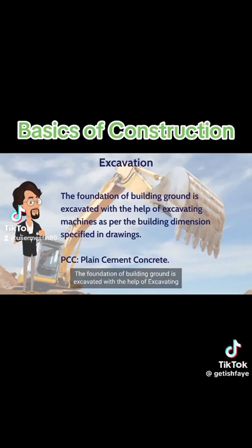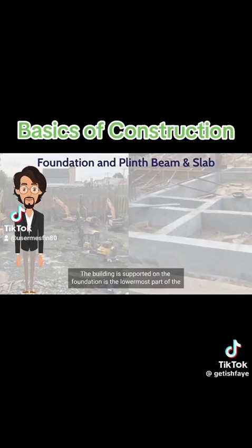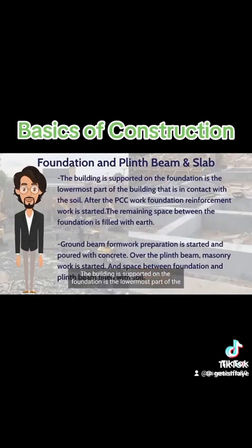The foundation of the building ground is excavated with the help of excavating machines, as per the building dimensions specified in drawings. In this foundation trench, a layer of plain cement concrete is laid in the dug portion before placing the reinforcements for the foundation. The building is supported on the foundation, the lowermost part of the building that is in contact with the soil. After the PCC work, foundation reinforcement work is started. The foundation is a vital part in construction as it withstands the entire load of the building.